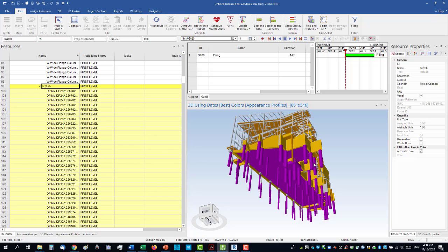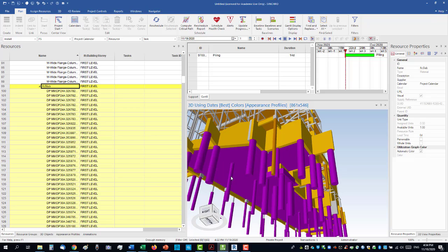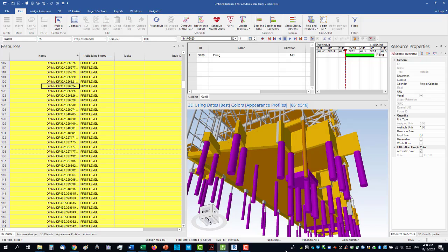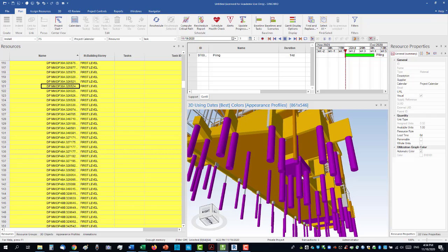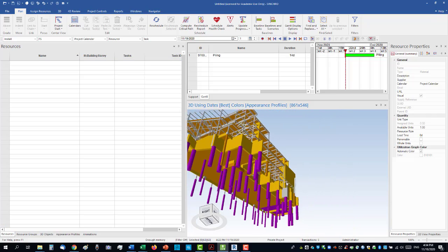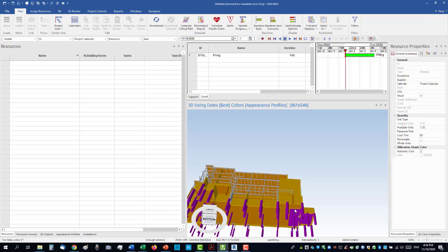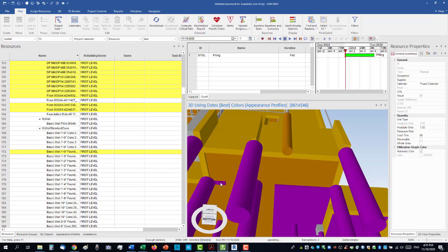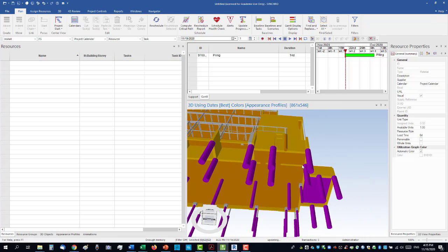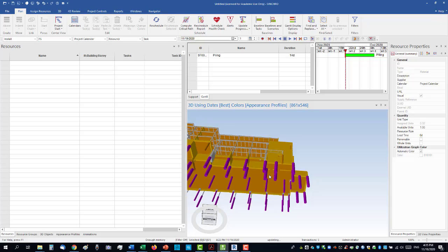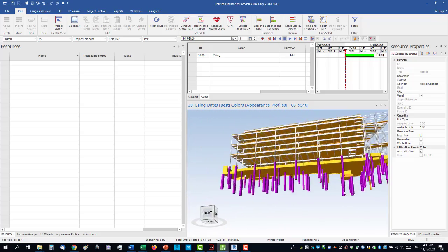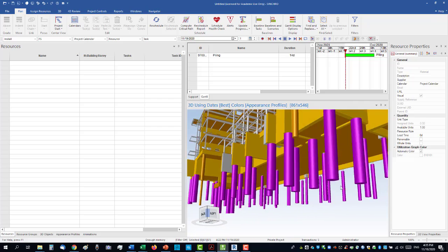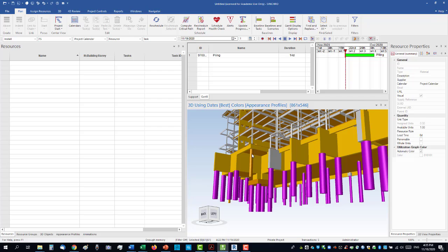So now I can unselect these elements that are not piles. So you click on Control, and then I remove that slab element. I remove the pile cap here. I remove this here. Oh, I selected something else by mistake. So I have to unselect it, then unselect the slab. And then I double check again. These are all the piles I have. Oh, there's one missing here.